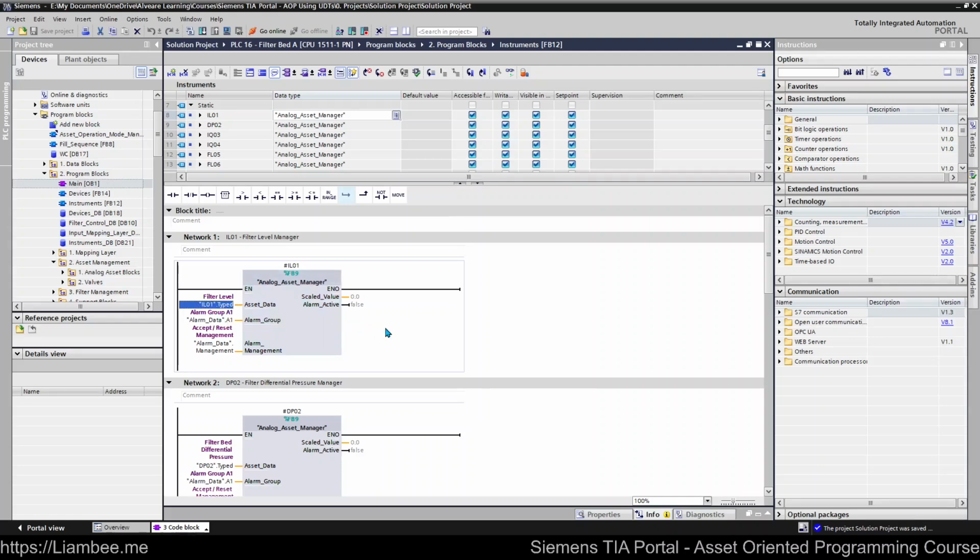And it's really important to understand that when you build your system, it might sometimes feel like you have information in more than one place, but from a containerized point of view, having everything that you need for that asset in one place that is a UDT and is able to be distributed across your entire project, across comm systems, across HMIs, across SCADAs, it makes a big difference to having to pick out information from different places.